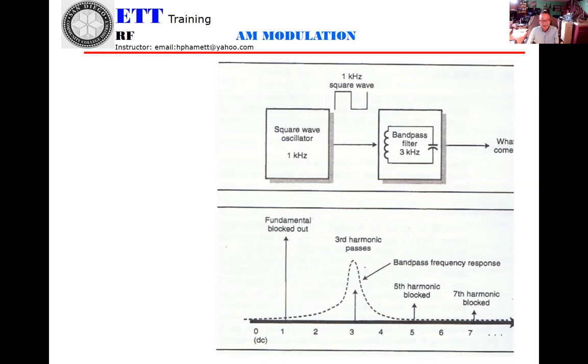Okay? The only thing is, when you connect the power to that oscillator, a square wave will automatically come out with the frequency you bought. 10K, you get 10 kilohertz coming out. However, the voltage will be only a 0 volt to 5 volt square wave.